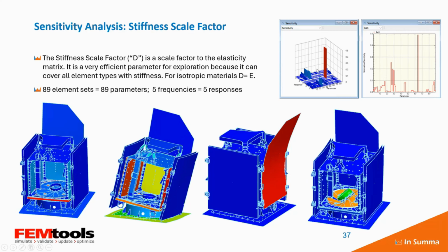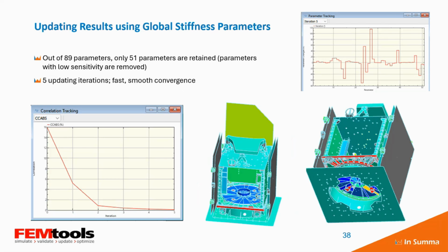We can look also in terms of a matrix. As you can see here, something really sticks out, and it's actually for mode number 3, which is the local panel mode. This red part is actually visible in the matrix with this high sensitivity value. And also as curves, we can look at each response, we can sum them. So there are several ways to look at the results.